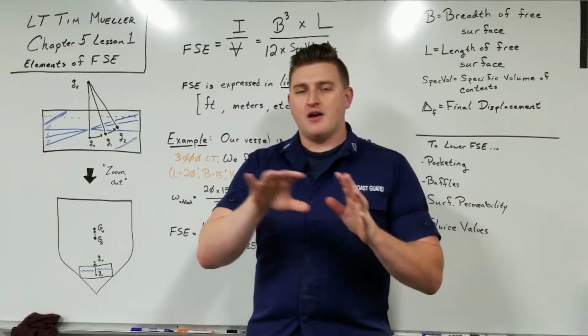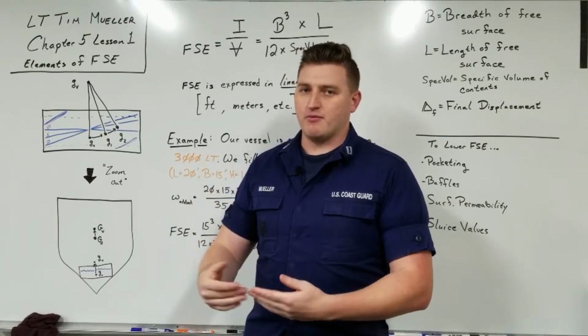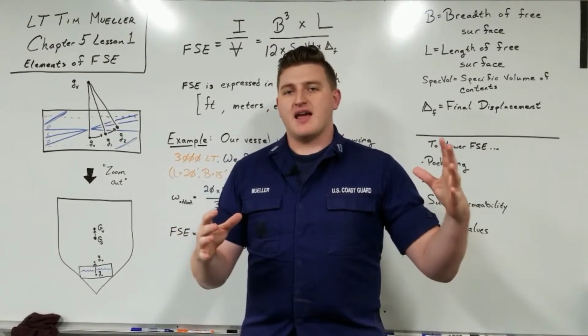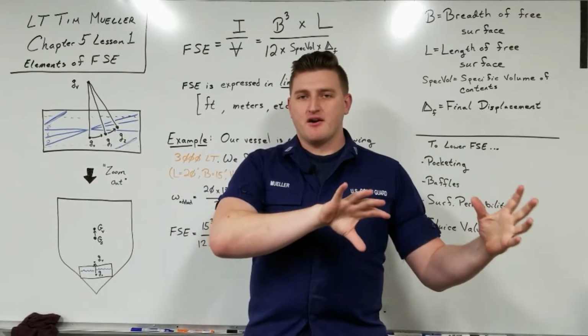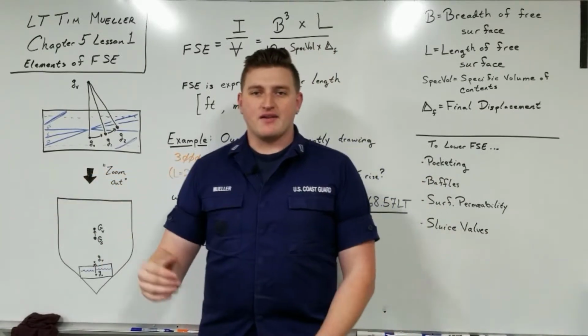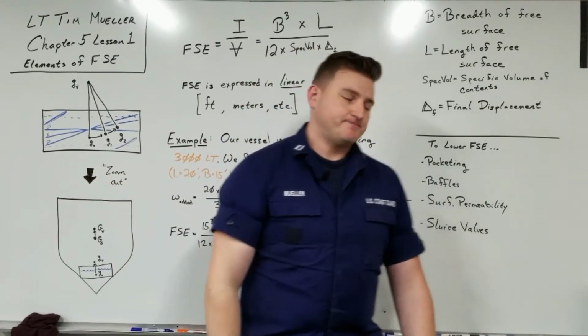Therefore, we're actually going to help ourselves a little bit in ship stability when it comes to initial stability and overall stability, because that water now, just like we saw with baffles, has to go further, it has to go around those engine blocks to go all the way to one side. That gives the ship time to roll back to the other side.